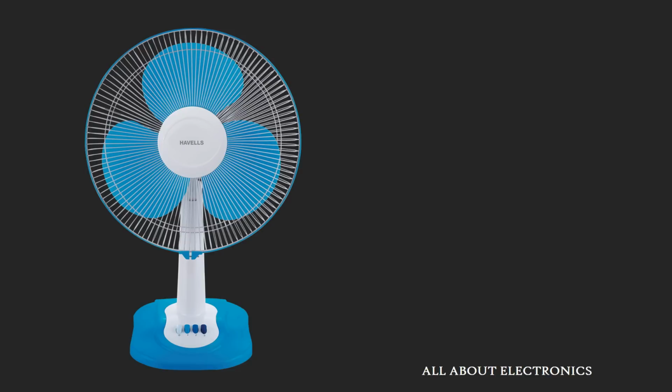Now, the true power is the fraction of the total power which is being supplied to this device. Apart from the true power, we also have a reactive power. As its name suggests, the reactive power is utilized in the reactive element of the load. Here, in the case of the fan, the reactive power is utilized in generating the magnetic field inside the motor of the fan. This reactive power does not contribute to useful work, but it is still required to generate the magnetic flux so that the motor of the fan can rotate.